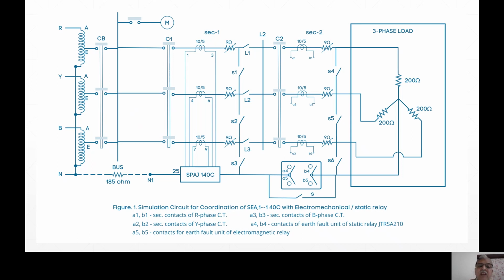Because we were understanding only that electromagnetic relay, disk type relay, that the E magnet is there and I magnet is there. Flux is produced, flux cuts the disk, therefore there are eddy currents. The interaction between flux and eddy currents produces the torque, disk rotates, the fixed contact meets the moving contact, relay operates, and therefore breaker trips.